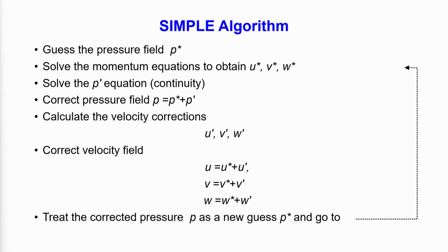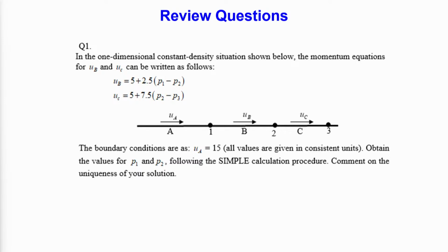The Ansys that you are going to use for your calculations uses some variant of this SIMPLE algorithm, because over a period of time different variants have come, like SIMPLEX, SIMPLER, and many others, but this is the foundation. If you understand this, you will recognize how velocity and pressure are coupled in a set of equations where you do not have a separate governing equation for pressure, and you are somehow manufacturing it by using the continuity equation. That is the essential learning that you get.